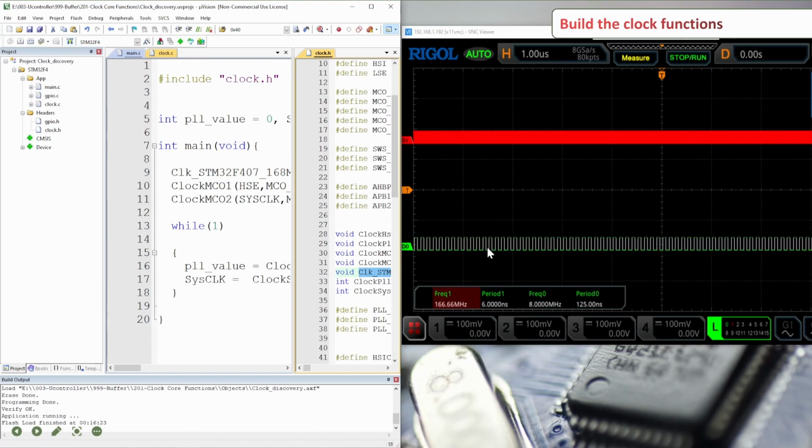It takes a bit of time. So you can see now that the output frequency here is 166. And if I check, it's flipping between 200 and 166, and we are reading a cycle of 6 nanoseconds, 5 nanoseconds, 7 nanoseconds per cycle, which is really, really good.